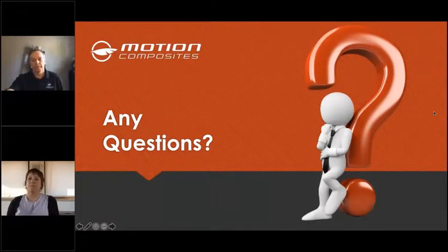Okay, and from Elaine Au, what are the caster selection considerations for self-propellers versus attendant-propelled chairs? Is there any difference? Yeah, I think that really what you're looking at is, first you have to look at the positioning aspect of it, the lower extremities. I see a lot of larger casters on chairs that are going to be pushed because maybe they're not as aggressive with lower extremity positioning. And a larger caster, if someone is pushing it, will roll easier for the person pushing, but you still have to consider the accessibility and the lower extremity positioning.